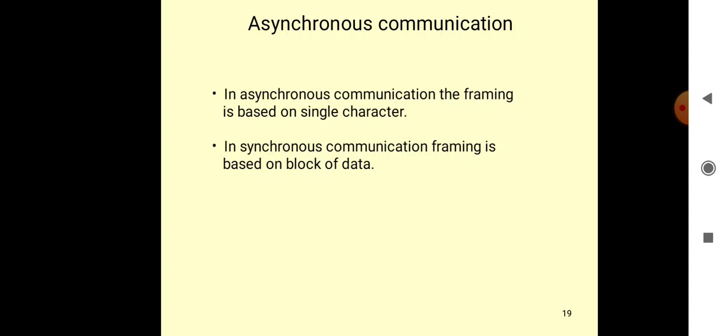In asynchronous communication, there is no need for perfect synchronization between the transmitter and receiver, and it is cheap. The disadvantages are that speed will be low, there are more bits, there is framing error due to mismatch in transmitter and receiver clocks, and it can be used for short distance communication only. More bits means the overhead will be more and efficiency will be low.